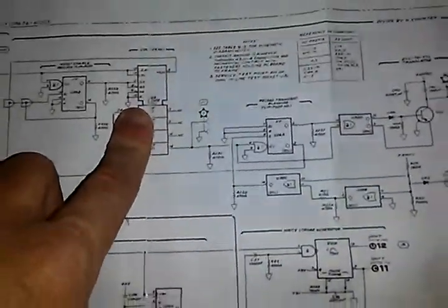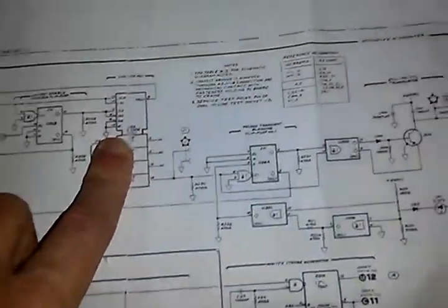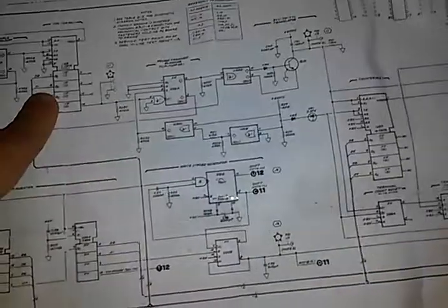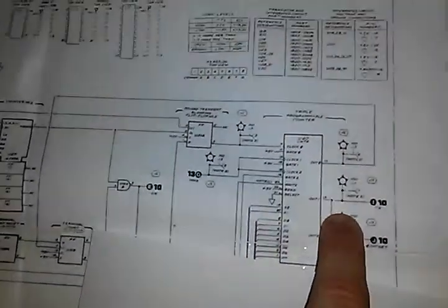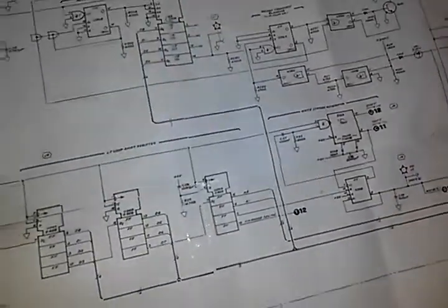Then after that, it always divides by 16. What that first count does is it delays this divide by N pulse by an extremely small window, which then is phase compared to the time base and is what causes the PLL to offset and change its actual frequency.